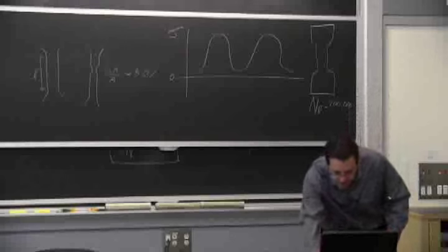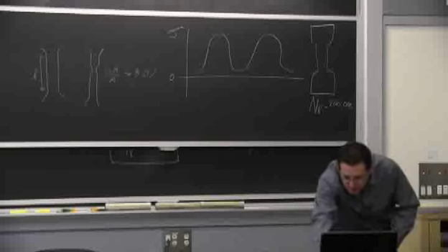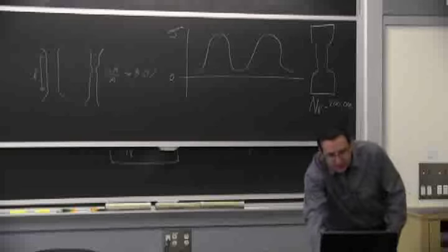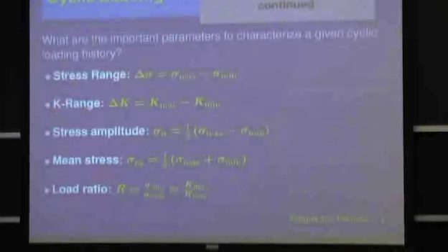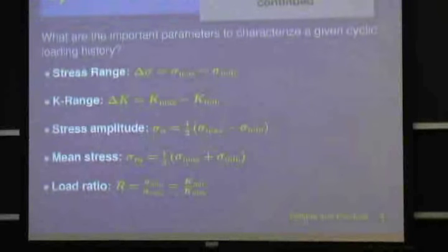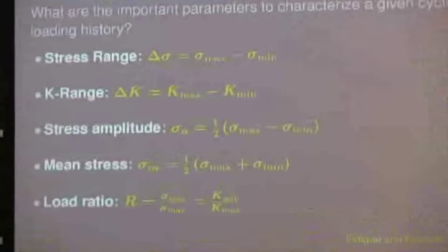Okay, so we take these values into account. What's the amplitude? What's the mean stress? And a bunch of definitions. And you have them in the notes. So I just want to stress that these are important if you're really going to take a curve out of any handbook or somebody gives you a curve for a new material. What's the loading ratio? What's the loading frequency? It's not there.